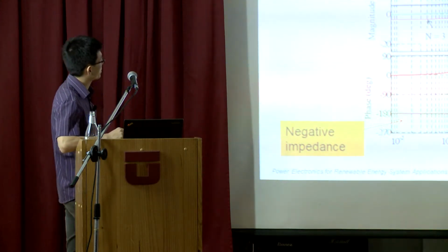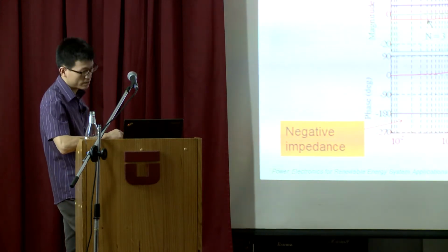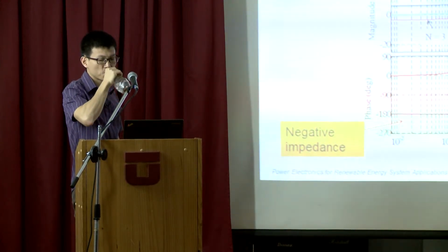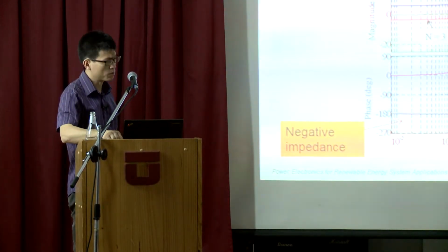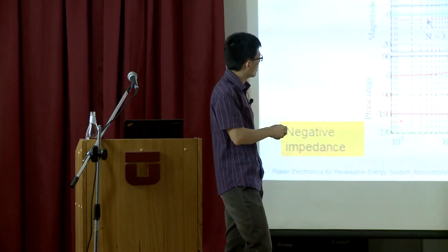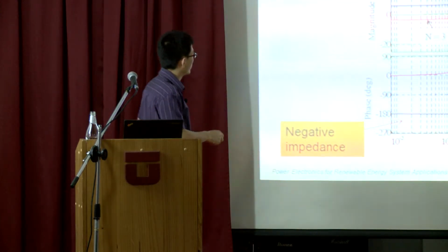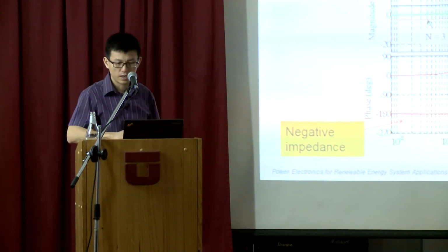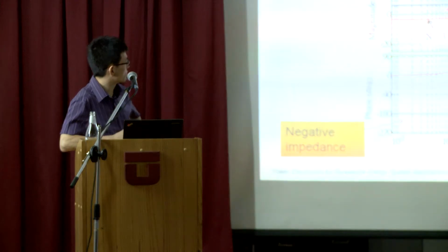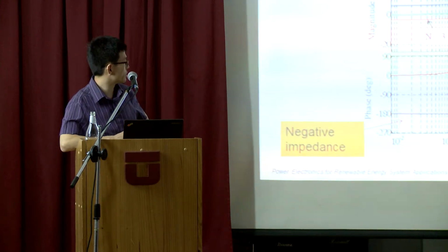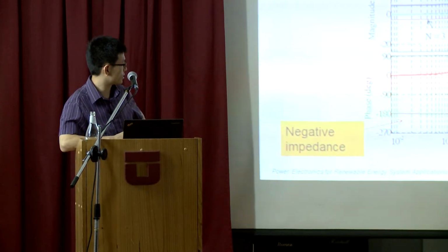What's interesting is when you connect them in parallel and see the difference between the systems, when you connect from 1 to 3, it is getting further away from the load impedance. In that case, I increased my stability margin. And again, the load here is the constant power load, which means negative impedance, as I showed here.